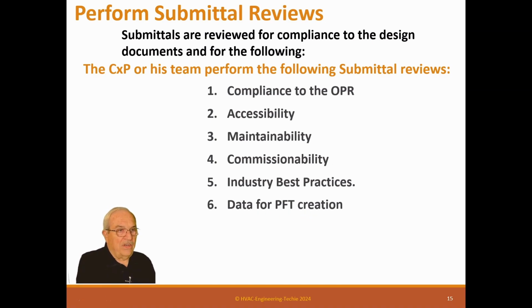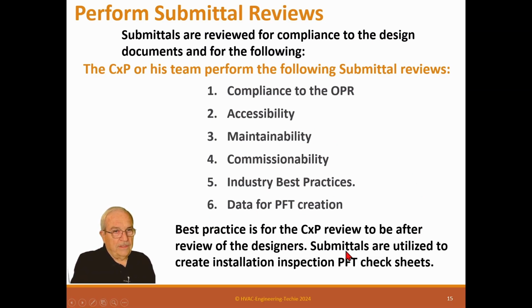Now, there is one caveat in submittal reviews. Submittals normally don't have just one-time review. They may take 4, 5, 6, 7 reviews to get everything correct in there, because there's a lot of people reviewing them. The owners reviewing them, the designers reviewing them, affected other subs' designers reviewing them, and the general contractor reviewing, and you're reviewing them. These can cause a lot of reactions, so you've got to stay up on the revisions to make sure something hasn't happened that might affect what you're looking at. This is just saying that you should look at them after the designers looked at them.